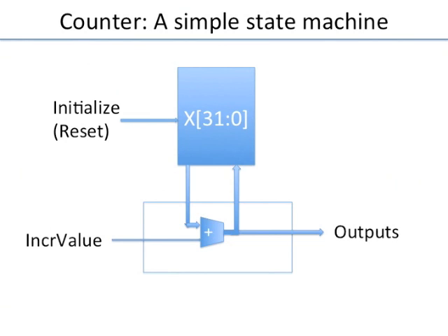You can make it more and more sophisticated. You can either make it increment, or you can have a signal which says increment or decrement, and the step, all that you can control. But basically, the current state is taken and modified by some operation to produce an output as well as the next state. So this is a very simple state machine.